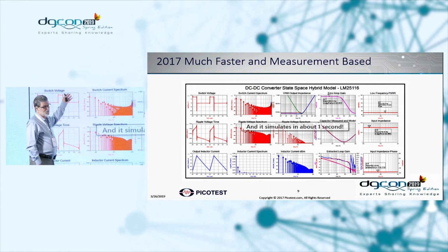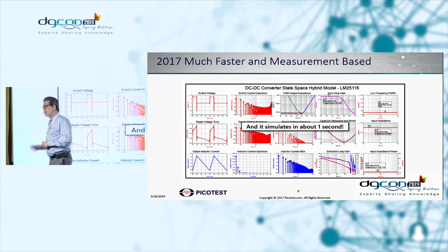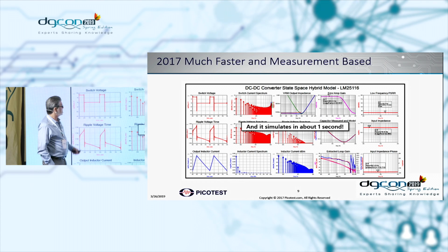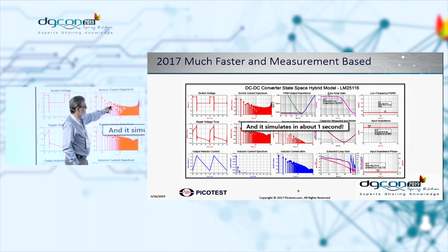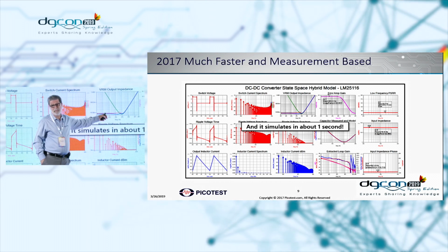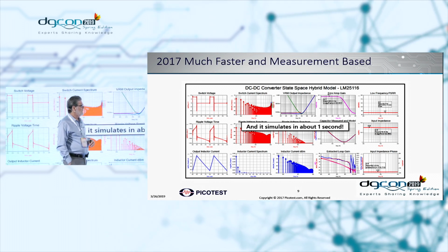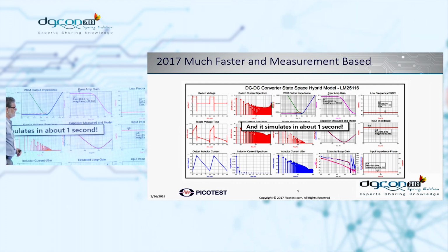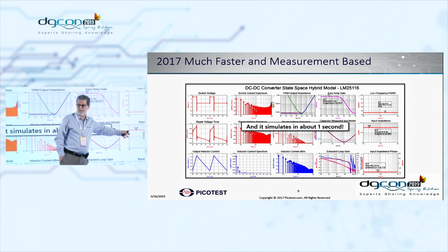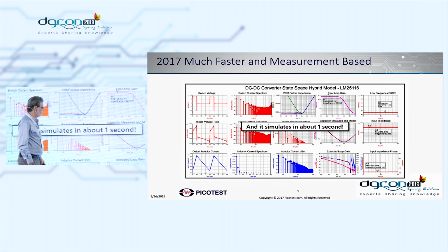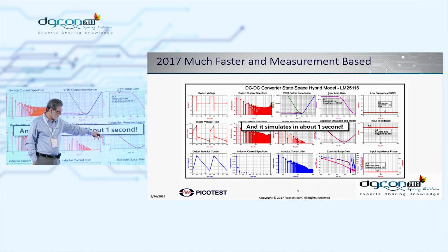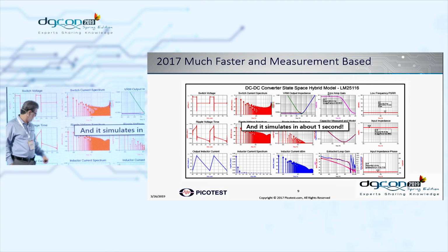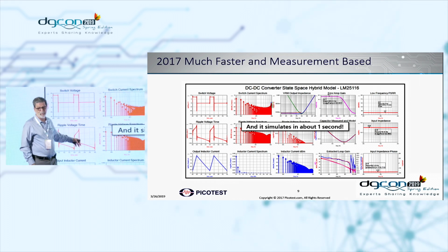I wanted to show you what a typical display looks like. When we simulate a VRM model, we're simulating a lot of different characteristics. For example, we might want to see what the switch node voltage looks like, and what its spectral response looks like. Of course, we're interested in the flat output impedance, which is our PDN tool. We need to know what the large signal gain of the feedback amplifier is. We need power supply rejection ratios. The input impedance of a switching regulator is negative, so we need to know what the negative impedance is. We need to know what the passive components look like. We need the control loop response. We have current spectrum for the inductors and ripple currents, and we even have output ripple voltage.